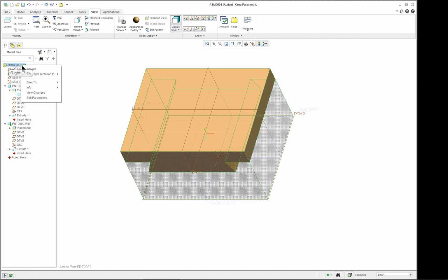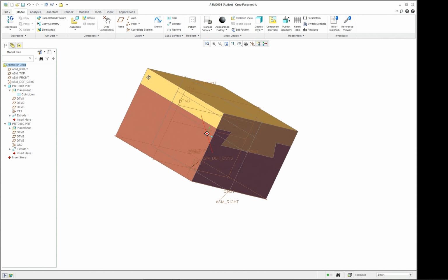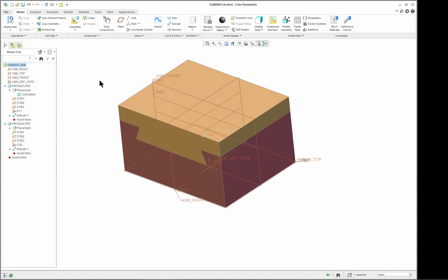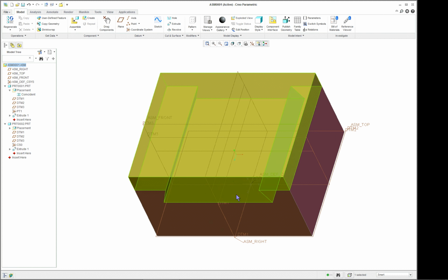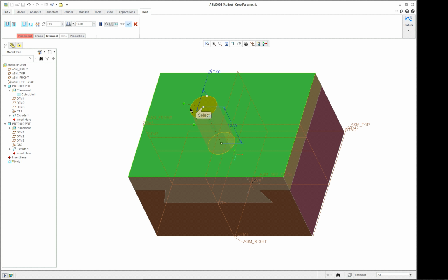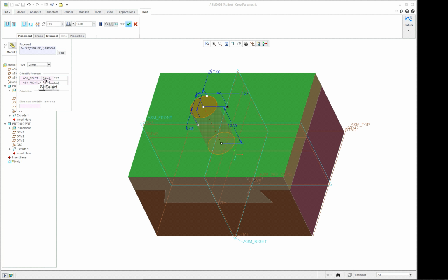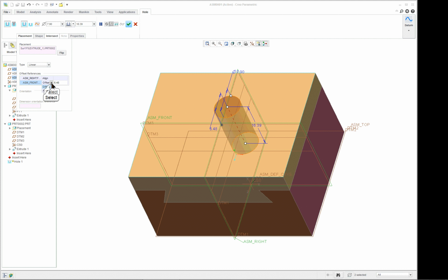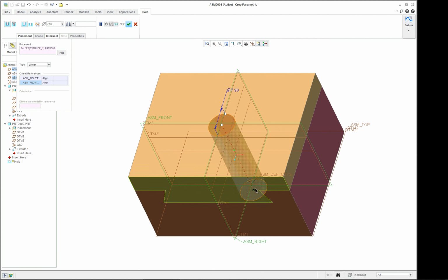All right. Okay, so let's activate the assembly. Got a couple of parts here, stuck together. No constraints because we're using external references for it. And I think what we're going to do now is put in a hole, but this is an assembly hole. And we will locate the hole just to place it in the very middle. And we will align it so that it is locked into the center. And then we're going to use our through all handle here.